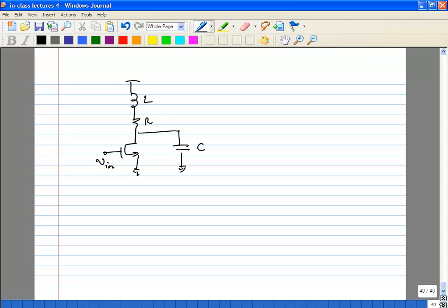What you are effectively doing is the inductor adds a 0 to your transfer function. The magnitude of the 0 increases as a function of frequency, so over a small range you are going to use that to improve your gain. If you look at it in the time domain, what does the inductor do? The inductor doesn't allow the current inside it to change suddenly. If your Vin is a step, the step response is a good way to measure the bandwidth of the system. The inductor tries to keep the current constant, so most of the charging current comes from the capacitor. So the voltage across the capacitor, which is what you are interested in, can rise much faster.